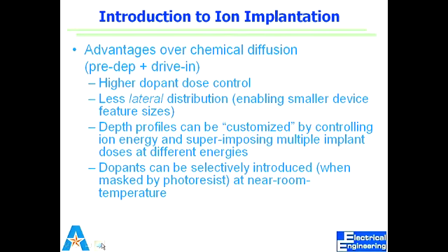And a very interesting, very important part, it's a low temperature process. When it's a low temperature process, I probably don't have to grow oxide and do etching. All I need to do is apply photoresist, do lithography, and I'm ready to do implantation, right? Because resist can withstand it. There's no issue of resist degrading with temperature, unlike in diffusion. So it's a low temperature process, which means less cost and high throughput, right?